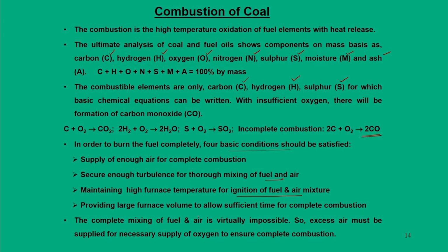But although these are hypothetical statements, complete mixing of fuel and air is virtually impossible. For that reason, normally we have to bear with supplying excess air, so that the necessity of oxygen can be realized during this combustion process.